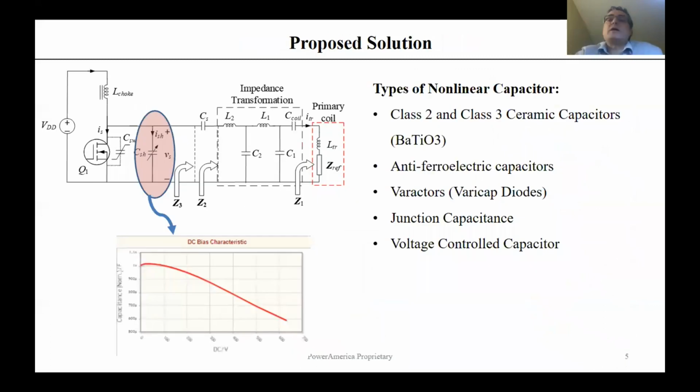To cope with the variable load problem, some researchers propose the use of active tuning of compensation circuits. The active tuning essentially negates one of the main advantages of resonant inverters: simplicity. Moreover, active tuning may not be fast enough in some cases to correct the tuning conditions before the switch is damaged.